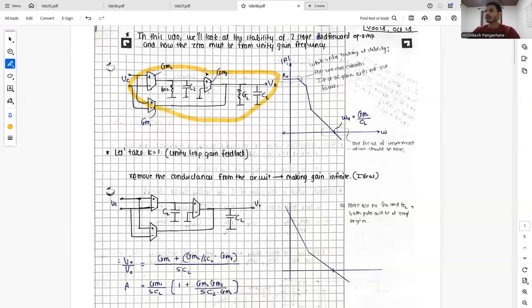So we have our opamp structure of the two-stage feed-forward opamp, and let's see its Bode plot, or its magnitude plot. While only looking at stability, we can consider that we have an ideal DC gain, because even though in reality the DC gain is limited and not infinite, that doesn't play a crucial role while defining stability.